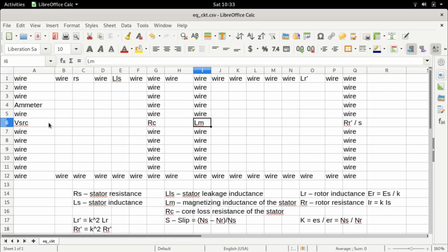Now if we apply a voltage which is close to the rated voltage, the impedance is so low that the machine will burn. The machine will simply burn. So therefore, when we block the rotor of the machine, we gradually increase the voltage, very gradually, until a current flows in the stator which is equal to the rated current of the machine.